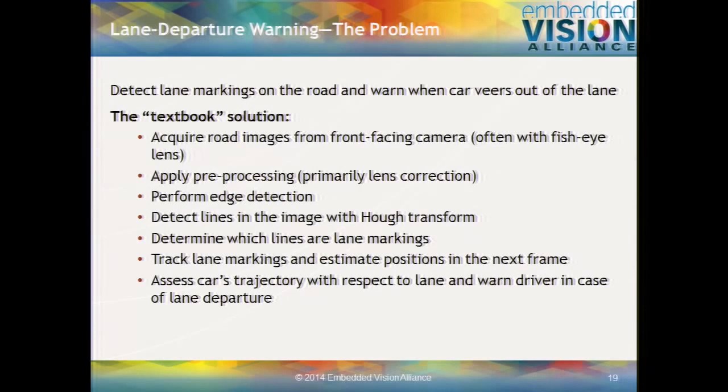So there are one or more cameras looking out, typically through the windshield, typically mounted up by the rear view mirror, so they have a similar view of the scene as the driver. They're looking at what's happening, initially specifically for other vehicles that you're driving behind, and looking for a situation where you are closing too fast on the vehicle in front. When they detect that situation, if it's a passive system, it's going to warn you with a shrieking alarm, perhaps. If it's an active system, it'll start by warning you, and then if you don't seem to be getting with the program, it will stop the car itself by applying the brakes. So that's one function that these ADAS systems provide.